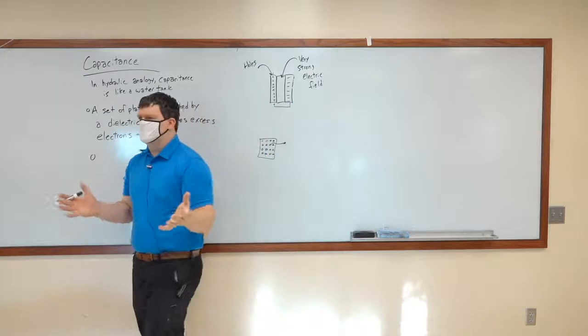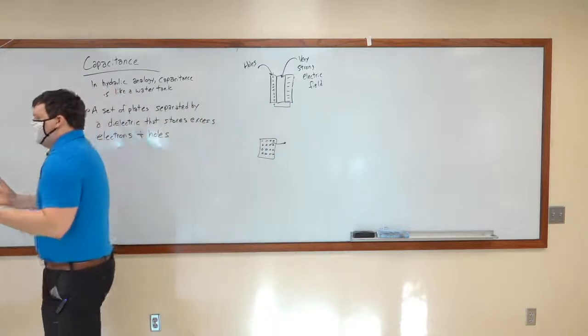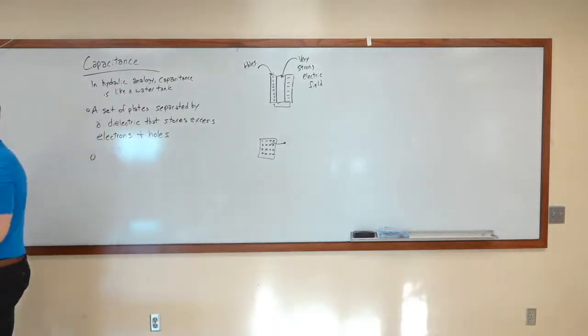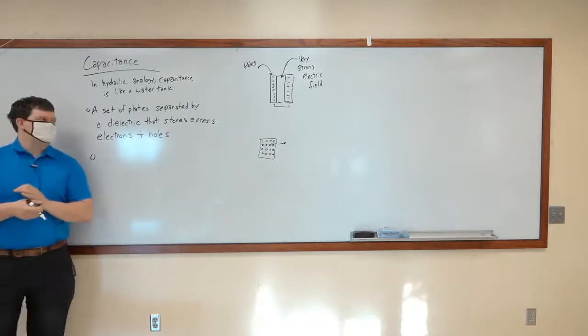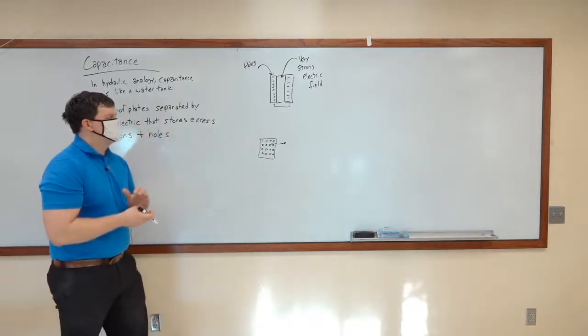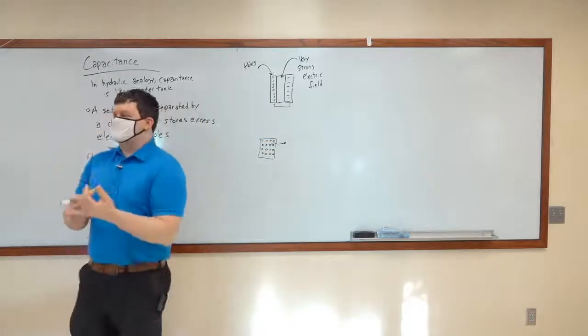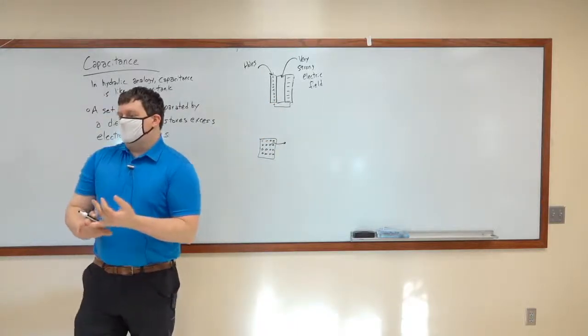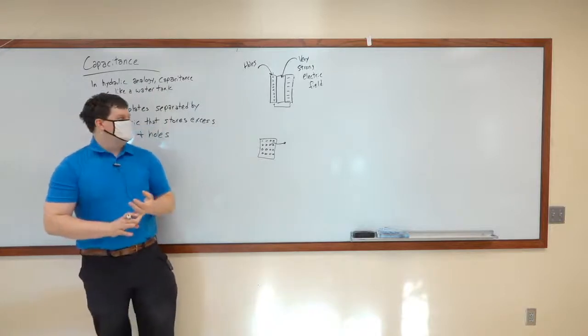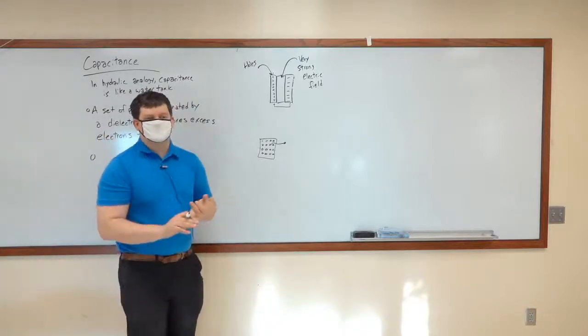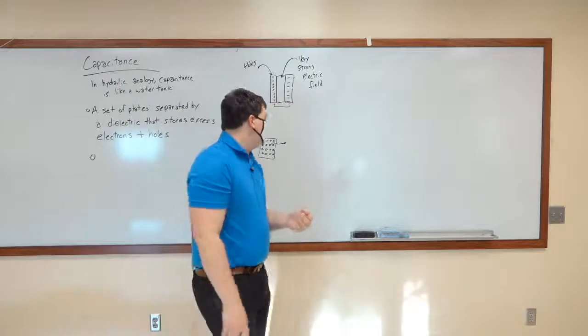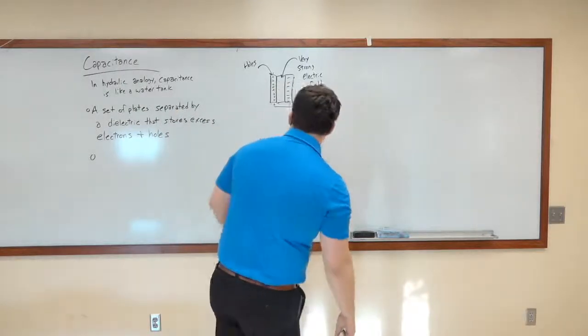It is the most insulating material you want. You don't want those plates transferring electrons. In fact, in some capacitors, if you do have a significant amount of electrons traveling through the dielectric, it will either cause it to start on fire or it will completely destroy the capacitance of the plates. It'll basically just turn it into a resistor. Okay? So, physical structure of a capacitor.